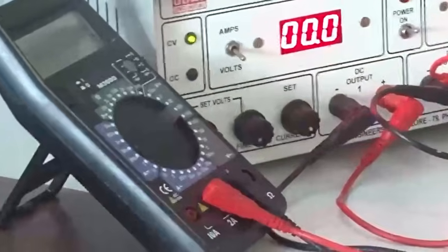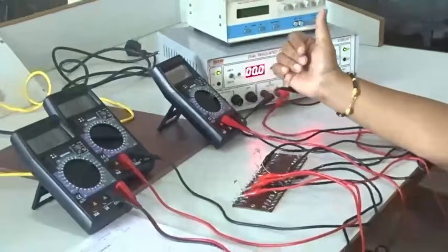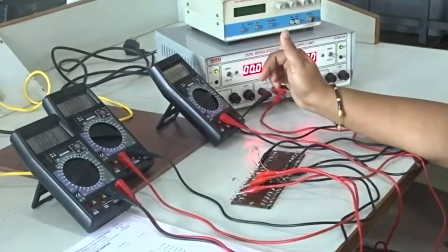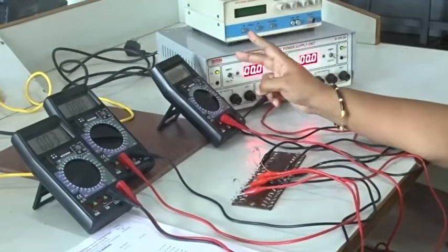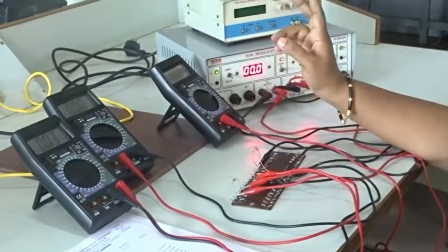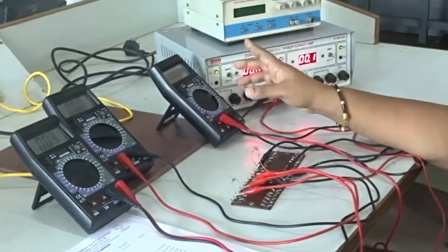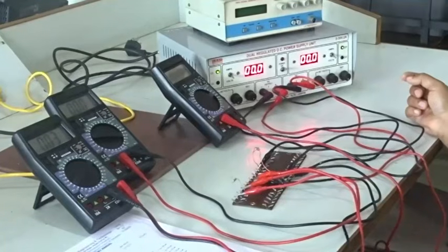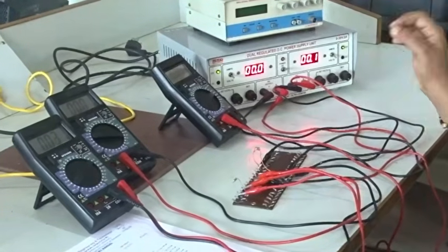The amount of current flowing in the base terminal as well as the VBE, that is base to emitter voltage, will get varied. So it is like common emitter configuration. We know BJT has 3 terminals, so it has got 2 junctions, base emitter junction and the collector base junction. This emitter base junction has to be forward biased, and the collector base junction has to be reverse biased. So it is just acting like a diode in these 2 junctions.